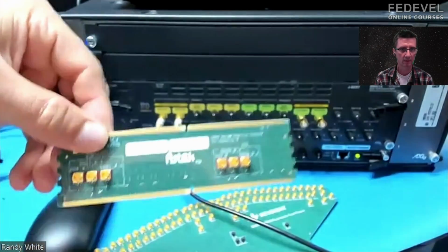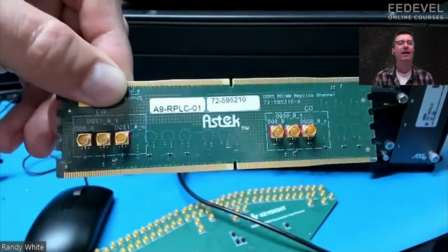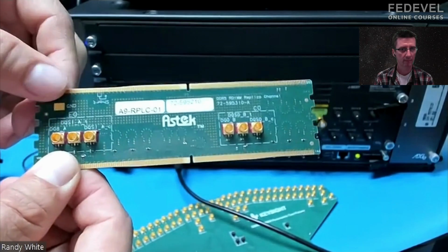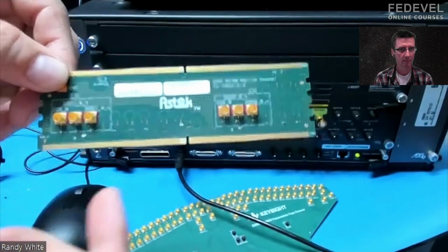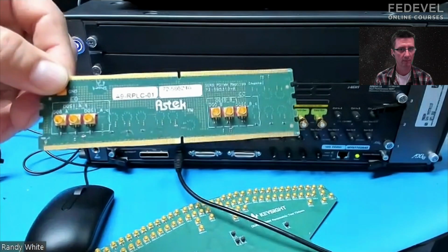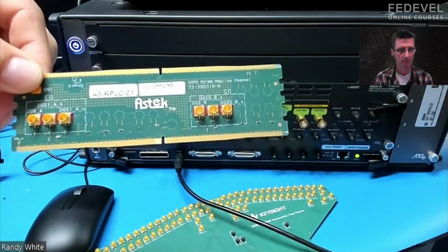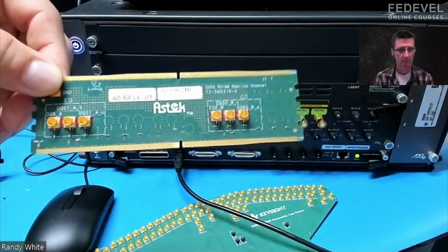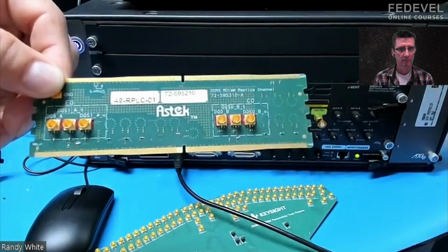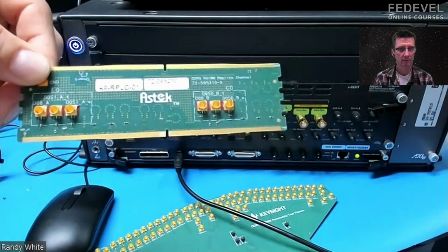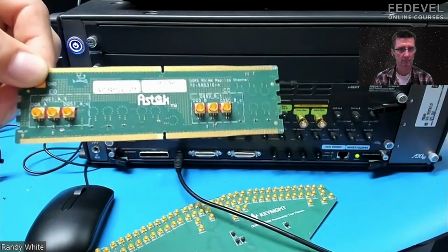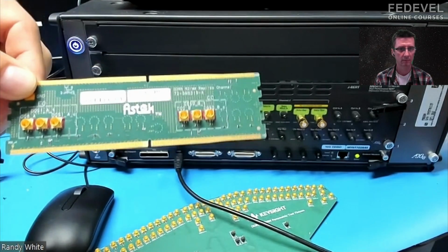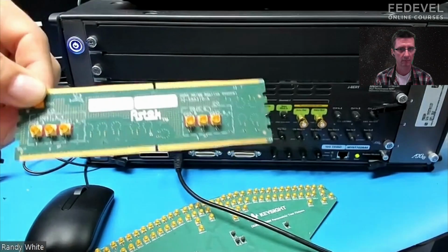Yep. Another fixture is what we call a replica card, and this, like the name sounds, it's replicating or duplicating or emulating a raw card. A raw card is the reference memory module design file, and you can download these from JEDEC. If you want to see what a UDIMM schematic or layout for a 2-rank or a single rank, these are publicly available.